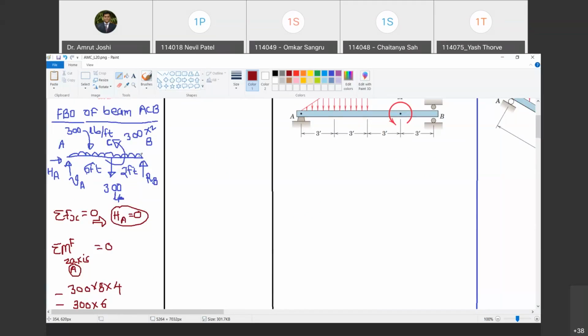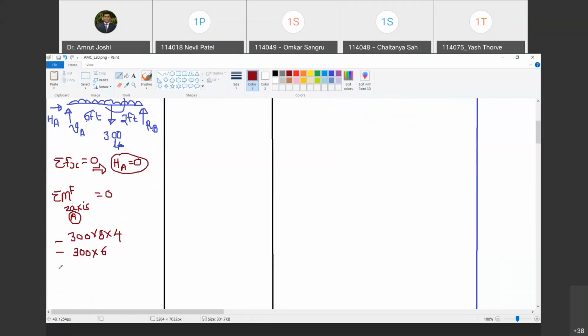As we have already discussed, the couple moment can be transposed anywhere in its plane. So even if it is acting at C, its effect at A is the same. Therefore, this couple moment, anti-clockwise, I have to take as it is. And as it is anti-clockwise, I am going to take it as plus 300 into 2. Do you agree with me?